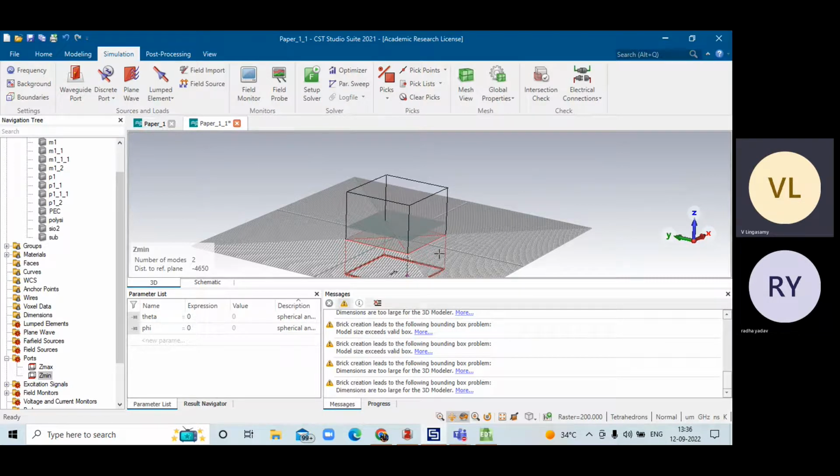For example, if you are designing a unit cell element, then you will see the grating lobes beyond maybe 0.7 lambda. If you go below 0.5 lambda, then you will see gain differences. So that's why it differs from use case to use case.